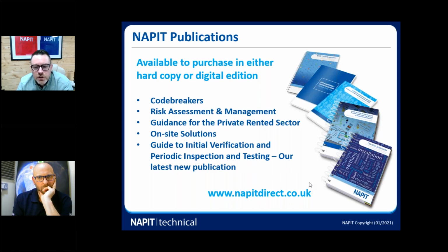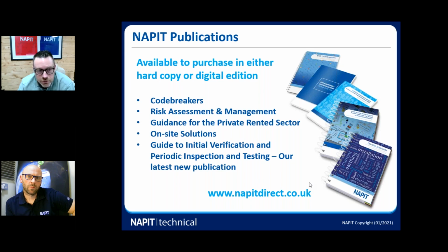You've got a high ZE, and that could be affecting your ZSs within the property, which would lead to an unsatisfactory situation within the property itself, and would require either further investigative work or some other action to be taken to make the installation safer.